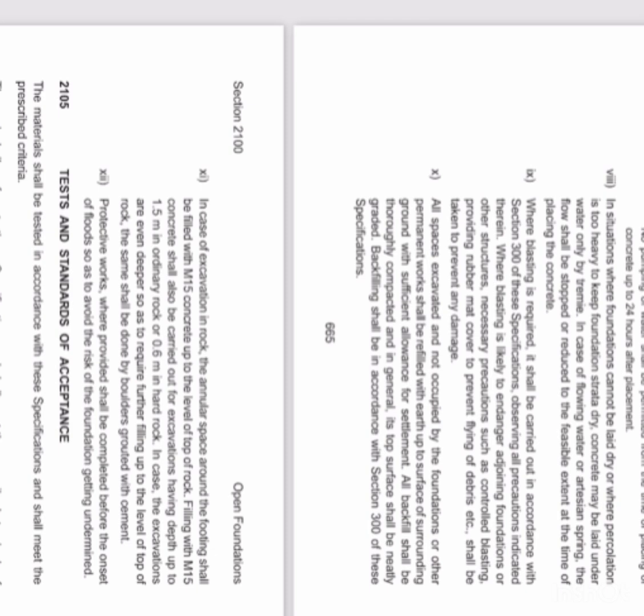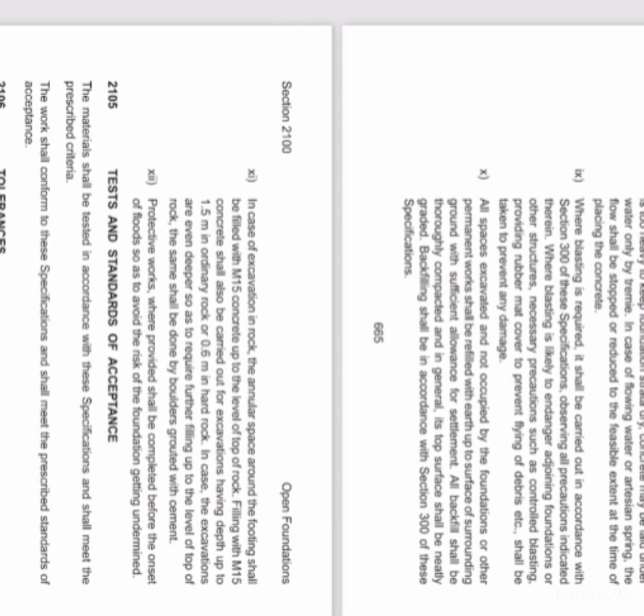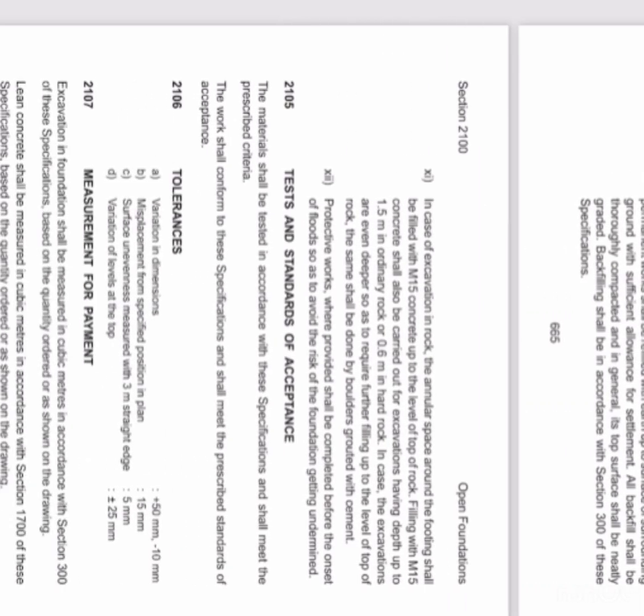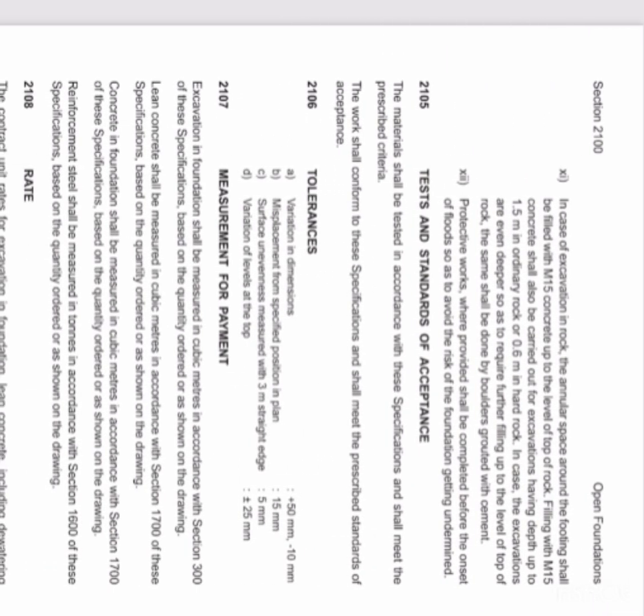In case of excavation in rock, the annular space around the footing shall be filled with M15 concrete up to the level of top of rock. Filling with M15 concrete shall also be carried out for excavations having depth up to 1.5 meter in ordinary rock or 1.6 meter in hard rock.